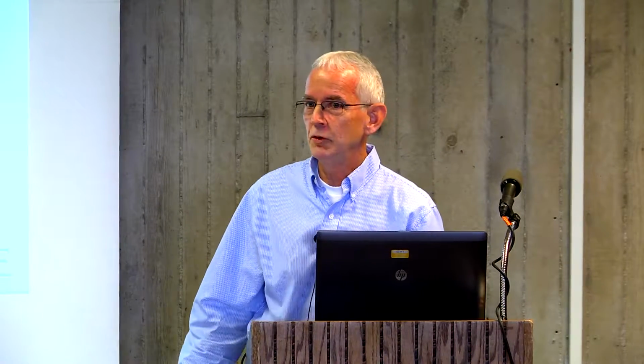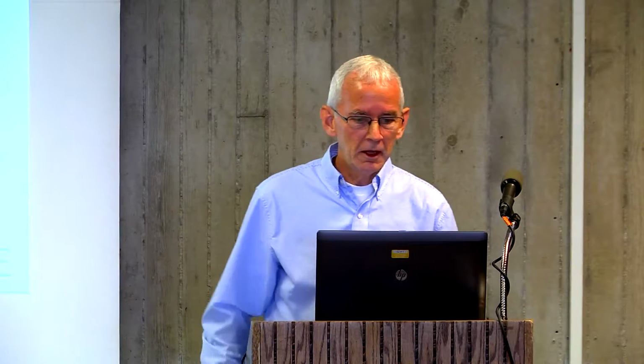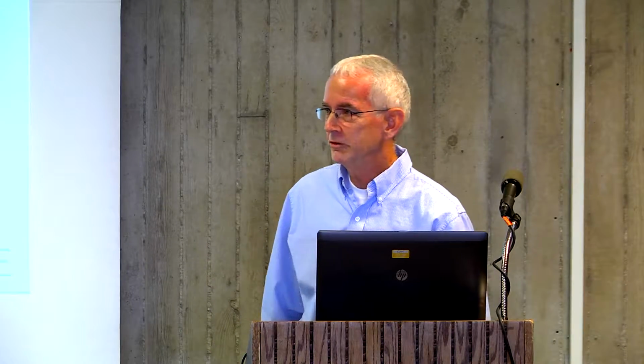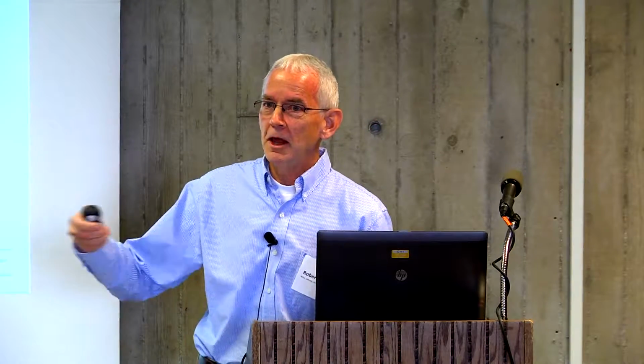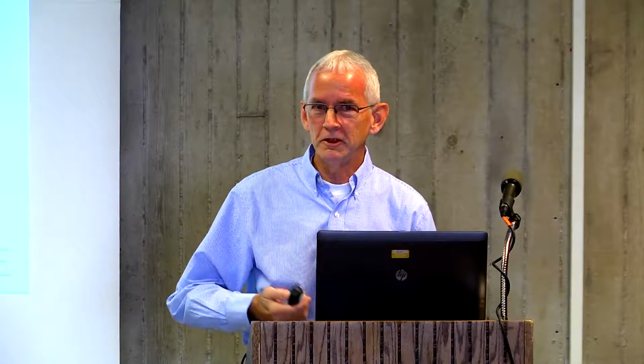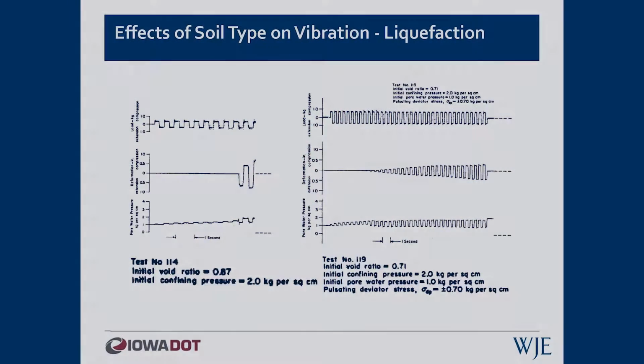And if you have a structure sitting on that soil, you could end up with settlement because the forces that are being applied to the soil, the pressure on the soil, may end up exceeding the bearing capacity if you've driven that pore water pressure up too high.